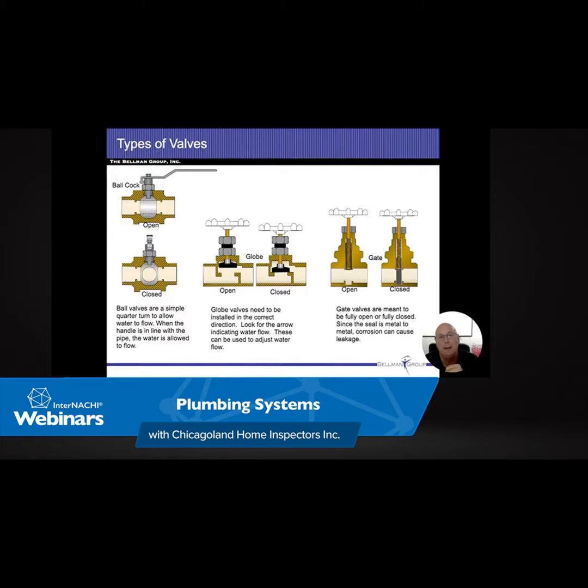So we responded, and we go in there, this room is filled with steam, I hear the steam going, and I was able to see down low that it was the water heater. We just went there, turned the gas off to the water heater, and then the pressure relief valve finally closed, everything cooled down, and the problems went away.